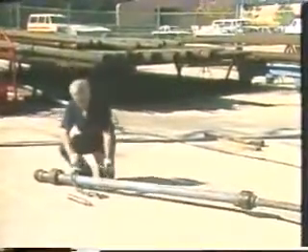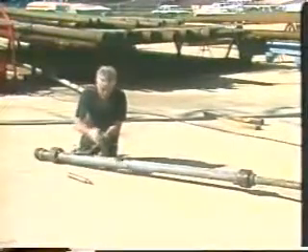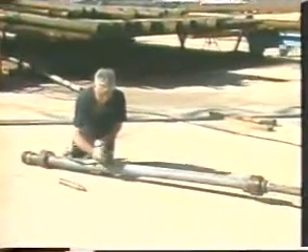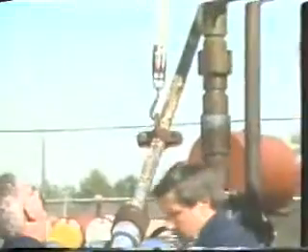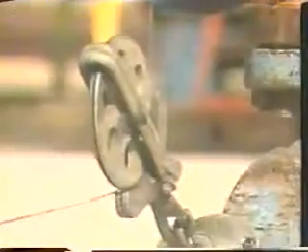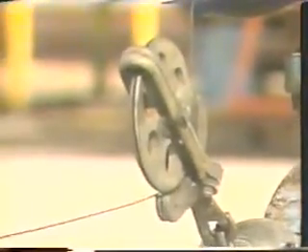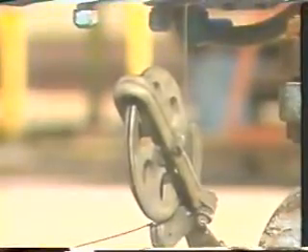Before the lubricator can be lifted into position on the wellhead, the tool string must be secured in the lubricator so it cannot fall out while the lubricator is being lifted. The wire is clamped to the lubricator with a wireline clamp. Next, the lubricator is lifted into position above the wellhead with the rope falls. A sheave is attached to the tree, and the wireline is threaded through this sheave.